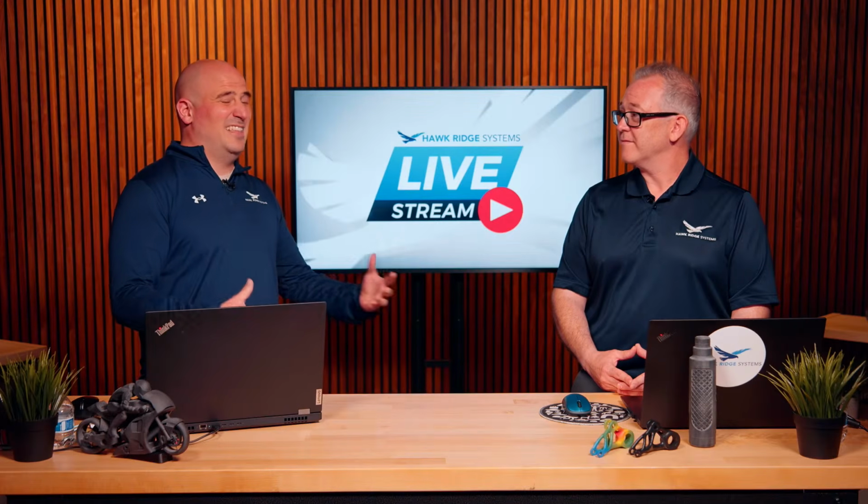When you have errors, that's when you have two mates that are conflicting each other. And errors are actually the place to lose performance the most. If you open up a model and it has the ketchup and mustard on it, the yellow warnings and the red errors, that's the first thing that you want to take care of, because that's where your performance is getting drained every single time. It's kind of like a room with 10 locked doors, and SOLIDWORKS is going to each door and trying to open it, and then it fails, and then the next time it gets a chance, it's going to try again to open the 10 locked doors.